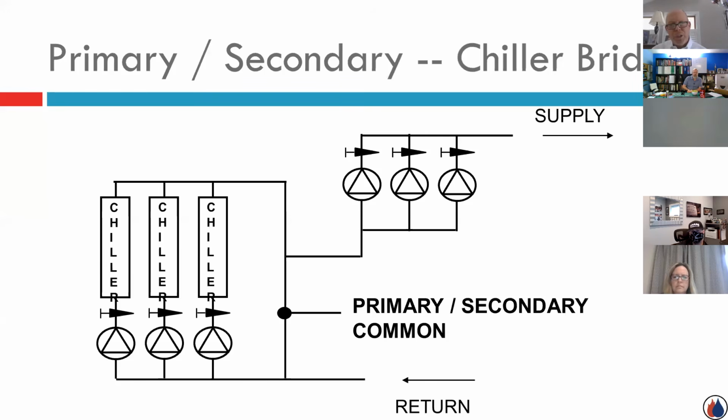Again, I mentioned chillers, very common. And here's that arrangement where they want all of that warm water coming back from the fan coils. They want to really load those chiller barrels with the warmest water possible. So they encourage that type of common pipe connection.